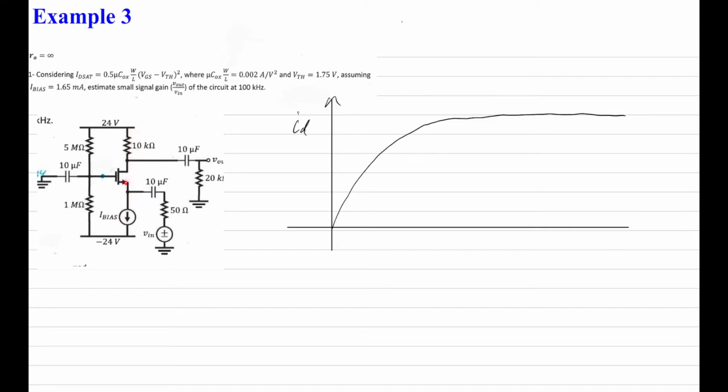Another point to note is that this point where the arrow is pointing out is the source. That's the drain. And the reason why that's the source, even though it's actually pointing in this direction, is because this is the direction of conventional current. So conventional current is actually flowing this way, which means that the electrons are actually flowing that way.